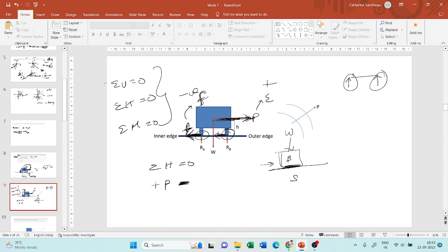If this friction coefficient is taken as f, then the friction force offered by this body is the vertical force times the friction coefficient, offered in the opposite direction. When you try to push the body, it won't move because it offers a resisting force due to this friction, which is equal to W times f, the vertical force into the frictional coefficient.